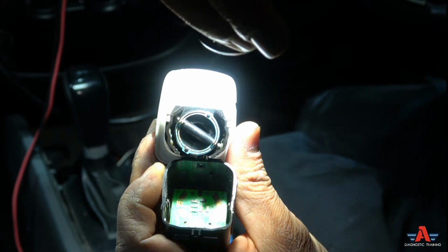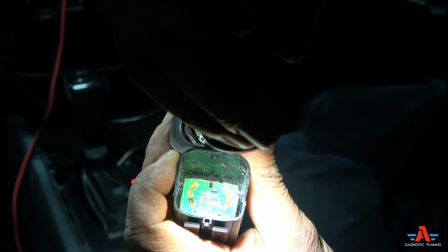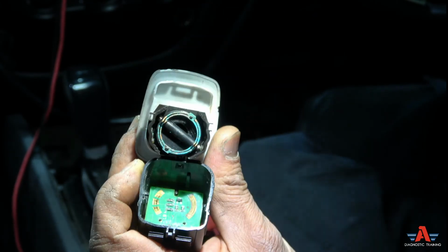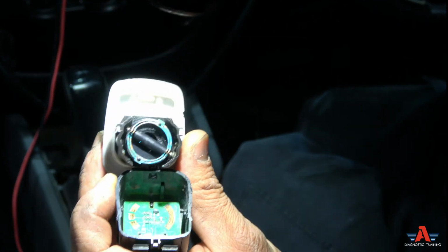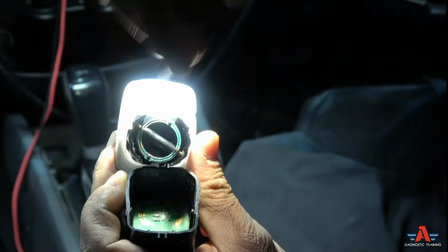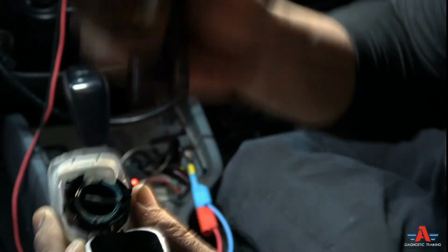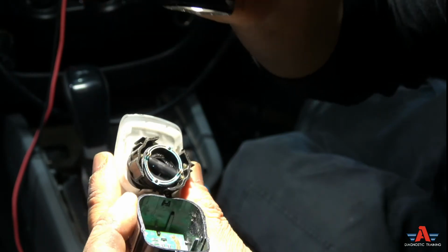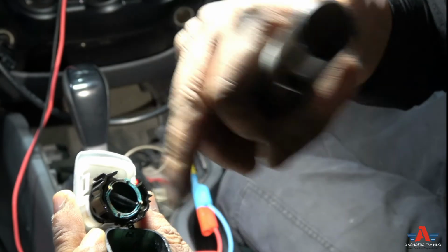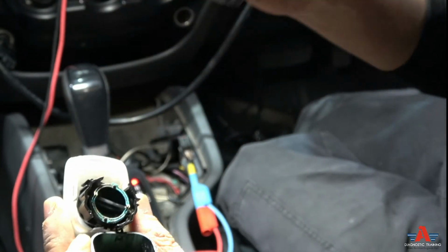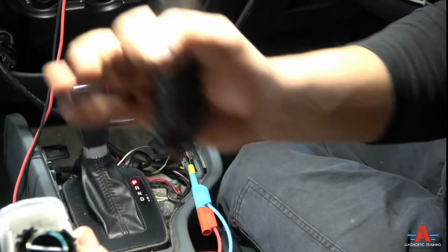So what happens is it's the same principle. We got 3 contacts for 3 different positions, and the other side is going to have the reference voltage on that big stripe there, one long stripe. The other 3 contacts on the other side are 3 different positions, and when you're turning the switch like this, right, see that turns, this is going to just pick the different position. That's it. And I'm pretty sure there will be a resistor to drop that voltage down to, like we saw on the scan, like 9 volts, 6 volts and 4 volts, something like that.